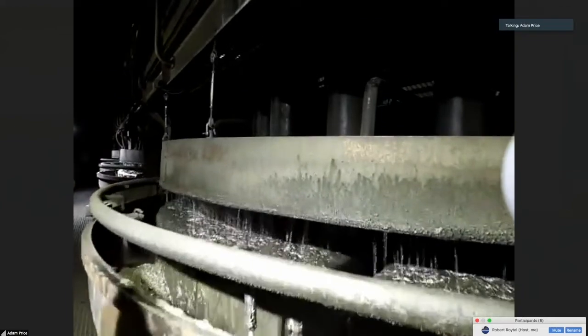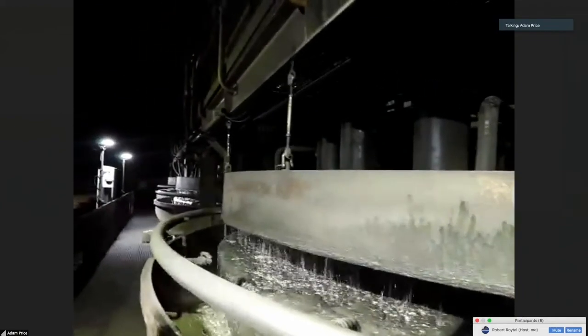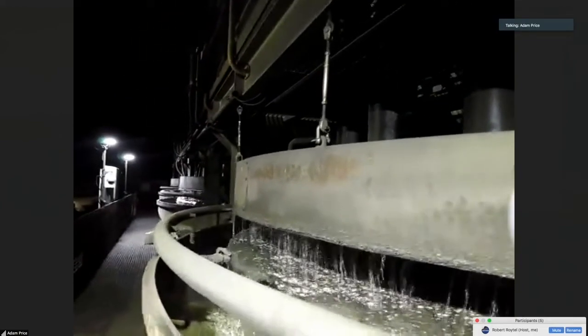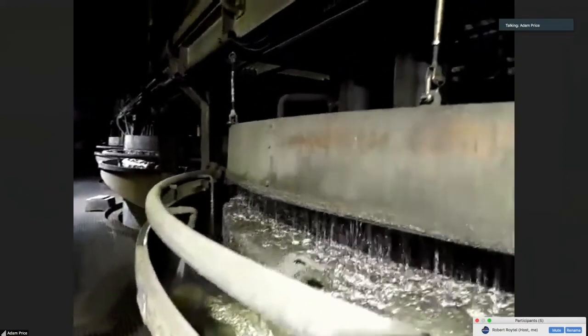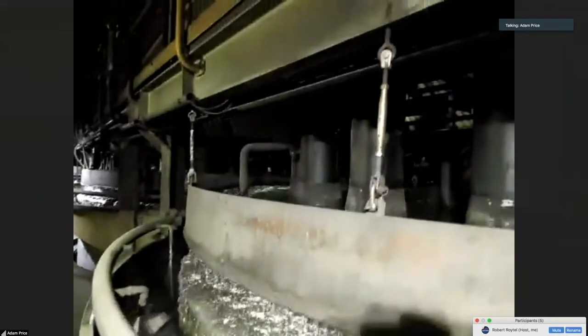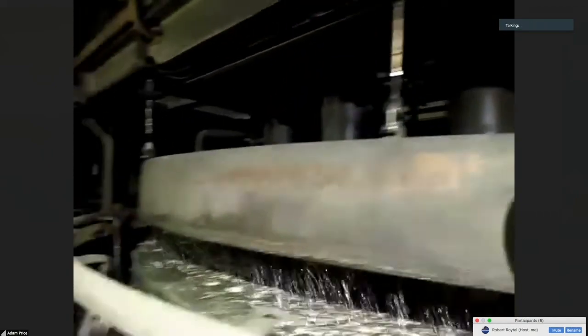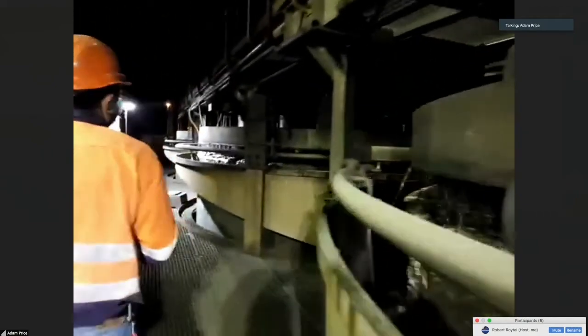The purpose of these Jameson cells is basically to clean our concentrate. They work in series with each other. First of all, we've got the scalper over here. The feed is coming from the rougher concentrate, and the scalper produces a big portion of the final concentrate. The tail would report to the middle Jameson cell, which we call the cleaner.